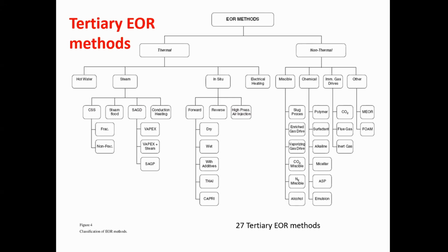I mean the reservoir in terms of type of rocks, permeability, porosity, the API of the oil, viscosity, the gas solubility in oil as well, the temperature of the reservoir, the pressure of the reservoir, the thickness of the pay zone, the depth of the well. All these are important factors you need to consider before deciding on which method I will use.